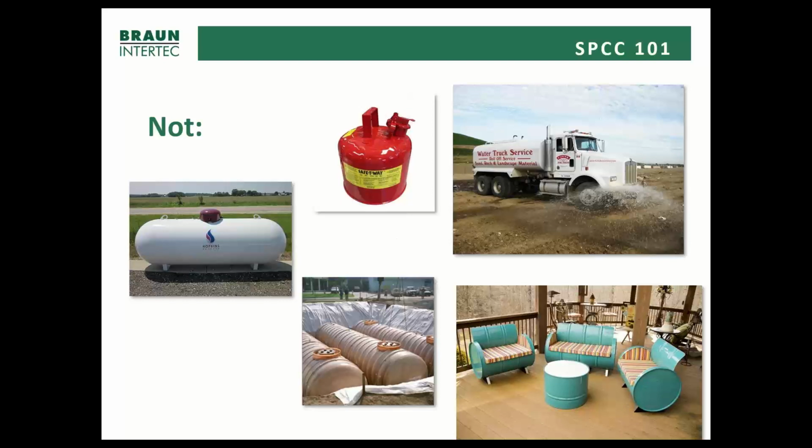And then there are containers that we consider to have been permanently taken out of service, is the term we use. Converted tanks that no longer hold fuel and are no longer capable of holding fuel. You may argue whether they're terribly comfortable, but I can definitely tell you that this set of deck furniture is no longer regulated by the SPCC rule.